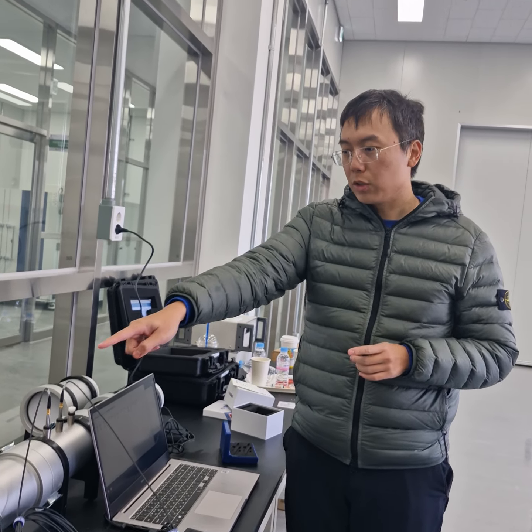Like every day. Typically we do it at the beginning of the test and also at the end of the test, and compare the calibration results. Not for the same sample, I mean just for the microphones. If the variation of the microphones' sound level is 0.5 decibel different, then we say the testing is not valid.